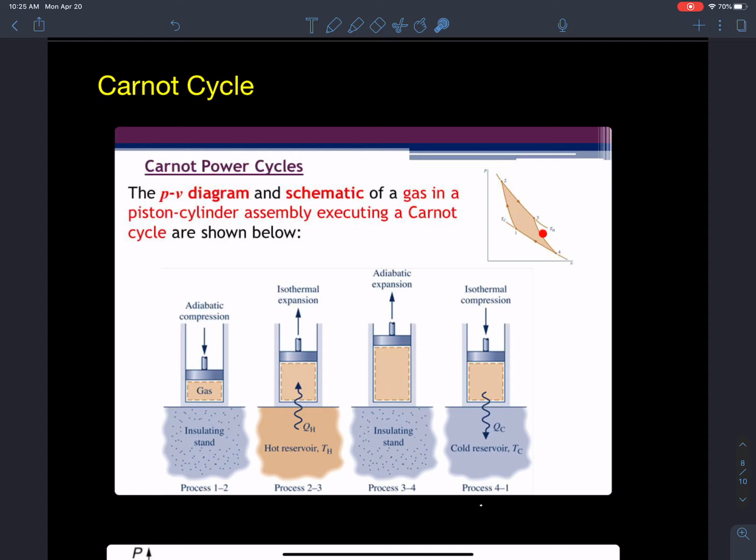And that adiabatic expansion results in changing the internal energy of the piston, which internally cools it. Okay, I'm not losing heat, I'm not venting it. Okay, and then from here, we will be doing an isothermal cooling back to the original state, back to the original state where it's compressing. To allow the piston to fall rapidly, heat has to be pulled out of the system. So there'll be a little bit of venting and injection of a colder gas in here so that it would rapidly fall back down and up and down, up and down. Okay, so that's called a Carnot cycle.